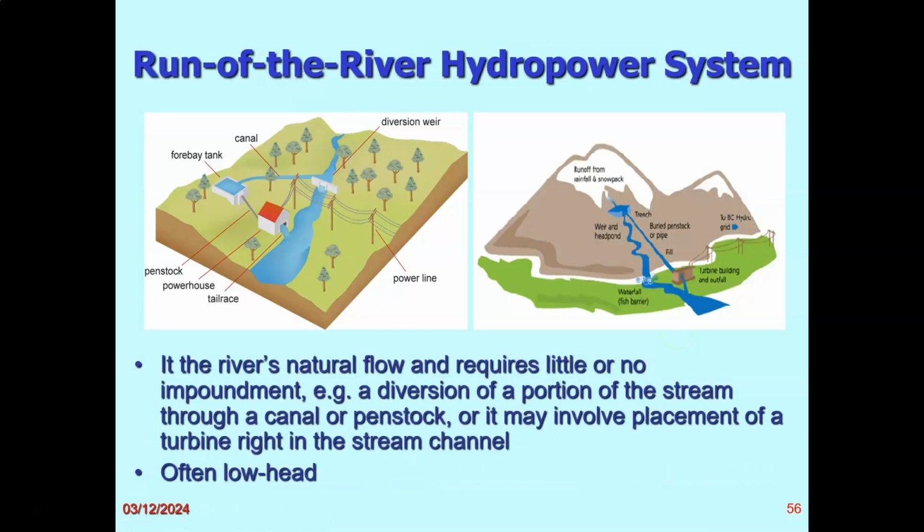On the other hand, as in the previous case here, you can use a diversion, so you can introduce a smaller dam here. You can see here, the impact is lower. You have a smaller canal here, a smaller reservoir with a smaller dam, a penstock, and then your powerhouse, and then you restore the water to the main river.